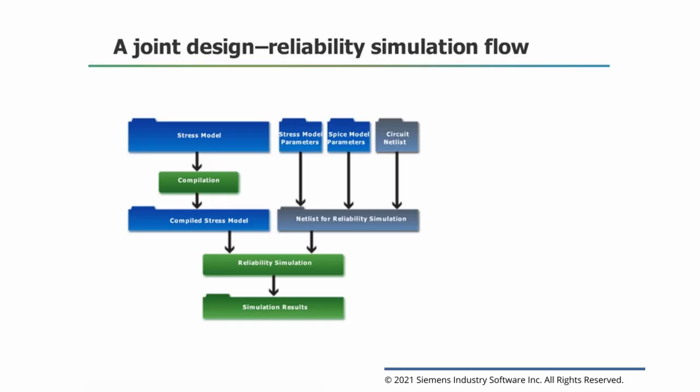The resulting quantity is then used to determine degraded values of the model parameters such as threshold and mobility, and using these degraded model parameters, a second simulation is run, which represents what would happen after n years of operation. In this age simulation, each device uses its own individual degraded model with updated values because the stress is device specific and so is the update. Fresh and age simulation results can be overlapped and compared.